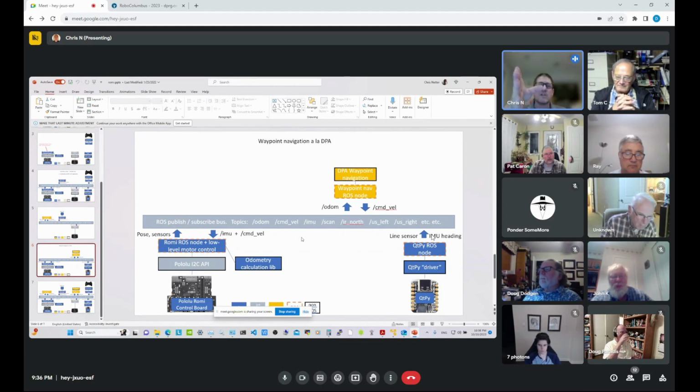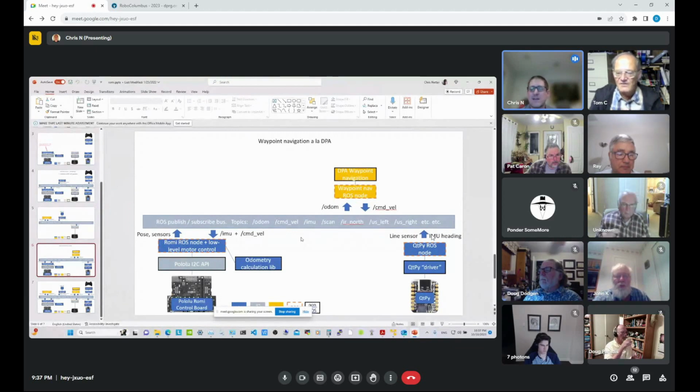It knows approximately where it's at. It knows the XY of the target. Okay, you drive towards it. Oh, something in front of me, so let me try to avoid that obstacle. But if you have an occupancy grid, at least a little bit, you'll more quickly know that you're going in circles or you're in a dead end and that sort of thing. ROS and the navigation stack have all kinds of sophisticated algorithms glued together to, in theory, give you a pretty sophisticated navigation capability. It's just really hard to get it to work on your own platform.